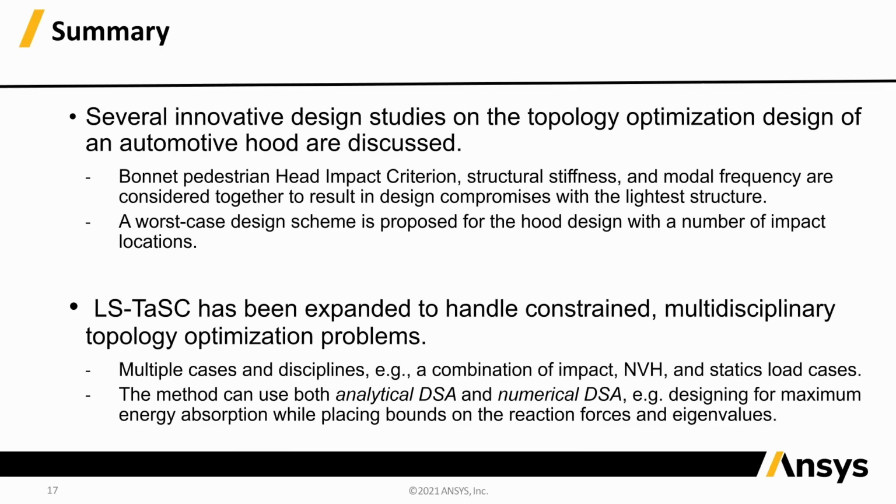In addition to that, you also have to pull in design codes, like the NCAP design code that we considered here with those many load cases. To handle that, we also proposed this worst case design study, which actually worked out quite well. All of these together become a practical industrial application and use of topology optimization to solve hard design problems. We also discussed the theory briefly, but the important thing is that we can use these for difficult industrial problems. So altogether, I think this is a new level of maturity for topology optimization.